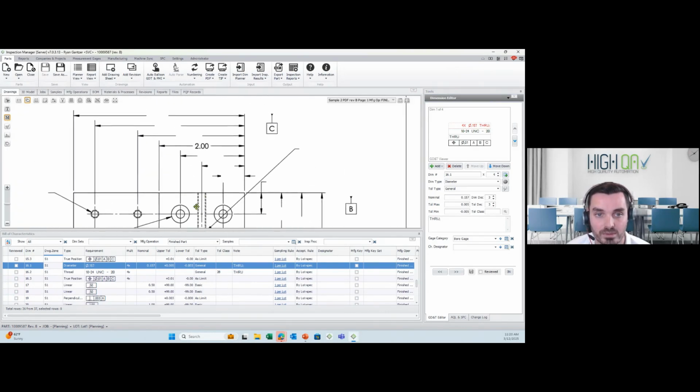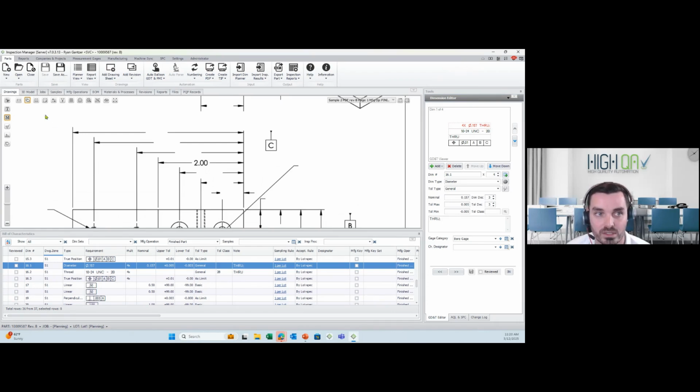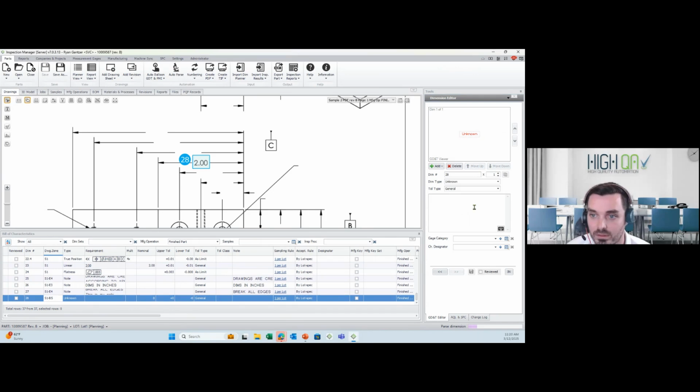So now it becomes very obvious what still needs to be ballooned. At this point, I can just zoom in and box select. Over here to the right-hand side, double check what the system comes up with. We have a 2-inch based on the decimal points, plus or minus 10 thou. Based on it being a linear, I'm going to use a caliper.